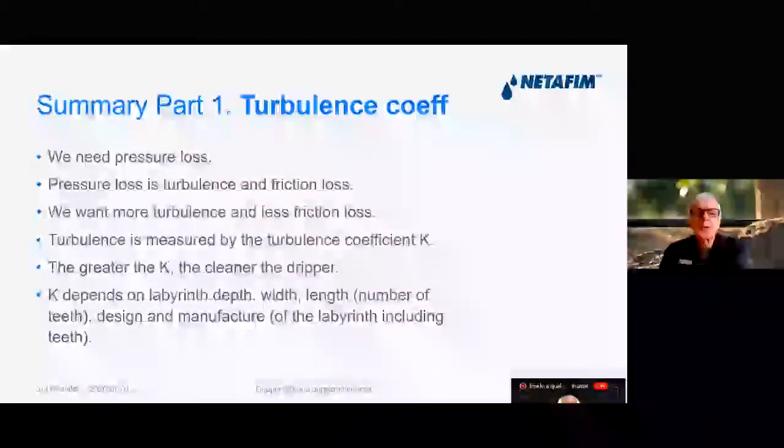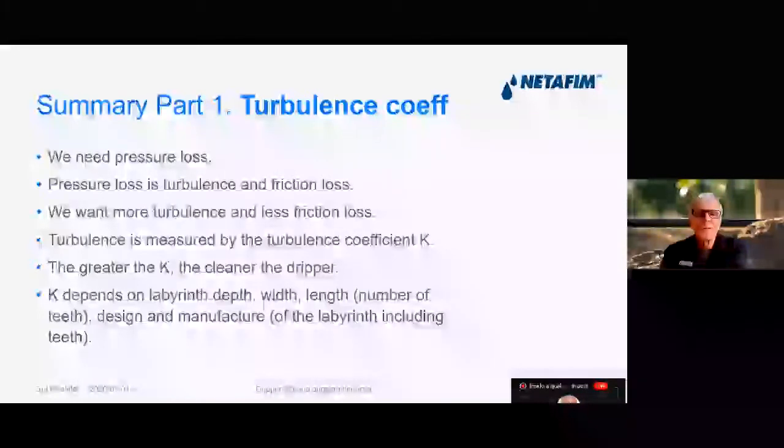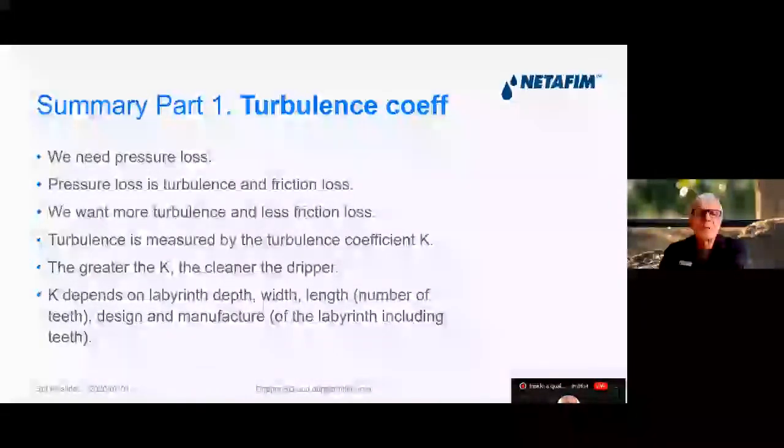And the turbulence coefficient, K, depends on the labyrinth depth, the width and the length. Length also concerns the number of teeth, and the design and manufacture of the actual labyrinth itself, including the teeth.